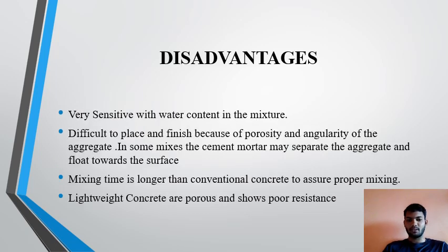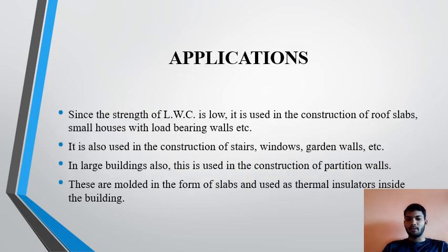Then disadvantages: very sensitive to the water content in the mixture, difficult to get a proper finish because of the property irregularity of the aggregate. In some mixtures, cement mortar may separate from the aggregate and float toward the surface. Mixing time is longer than conventional concrete to ensure a proper mixture. Lightweight concretes are porous and show poor resistance.